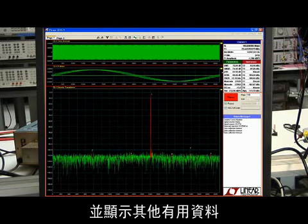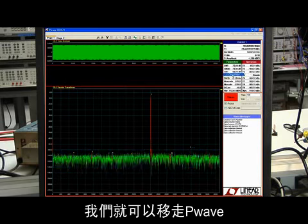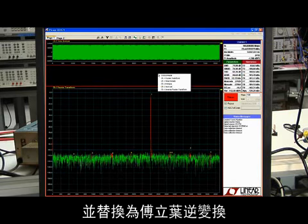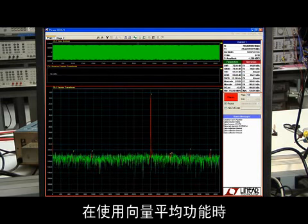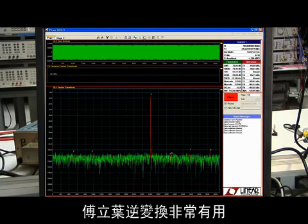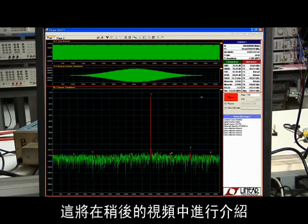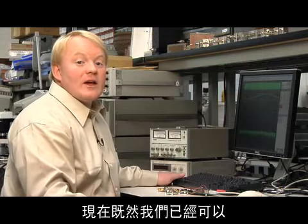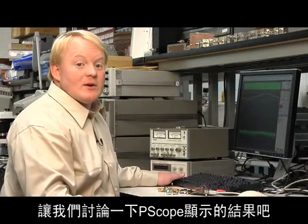It is also possible to change the displayed windows and display other useful data. If we click here on PScope, we can remove the P wave and replace it with an inverse Fourier transform. The inverse Fourier transform is useful when using vector averaging feature, which is covered in a later video. Now that we have the display showing what we want, let's discuss the results PScope is showing.